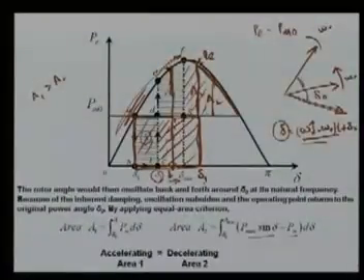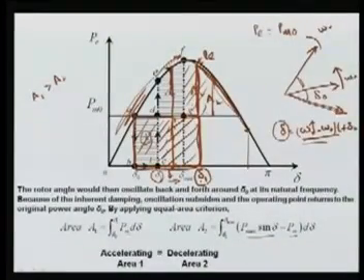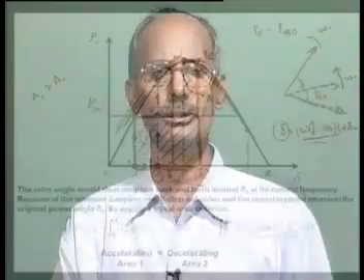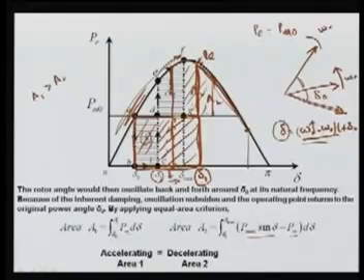So what we normally do is try to determine what the value of delta 1 should be. Here I am going to explain how large this delta 1 can be, meaning the fault can be cleared so that our system will be stable. Why are we so concerned about this? This is the maximum delta 1 at which we can clear the fault and our system will be stable. This is known as the critical clearing angle. If you are calculating it in time, then it is called the critical clearing time, CCT, and here delta 1 is your critical clearing angle.